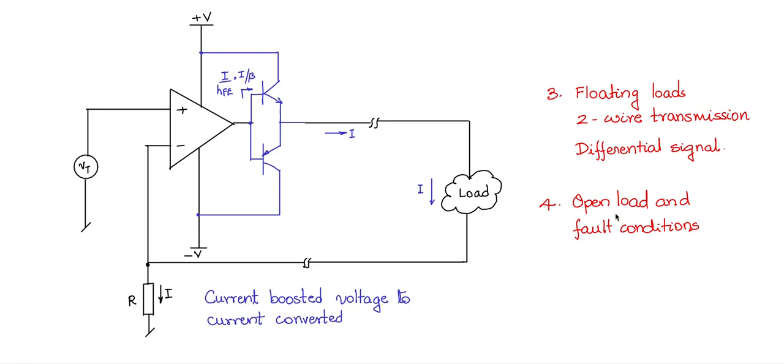In order to distinguish this, what is employed is that there is a minimum current that has to always flow through this external load or the long loop. That minimum current is defined as a standard, which is 4 milliamp. So 4 milliamps implies that Vt is 0. If Vt is 0, 4 milliamps is supposed to flow. If Vt is maximum, 20 milliamp is supposed to flow.